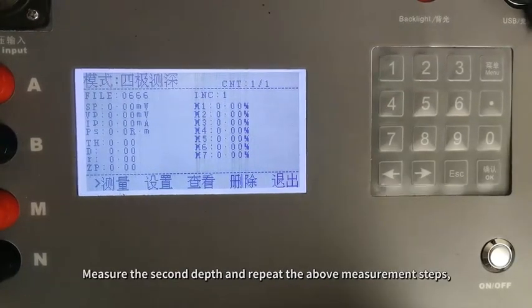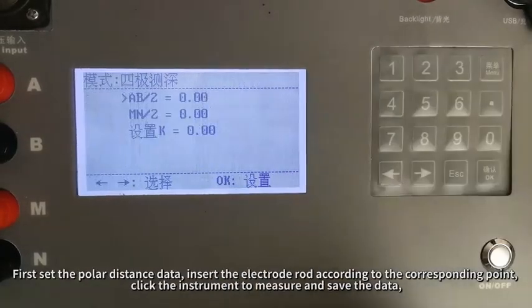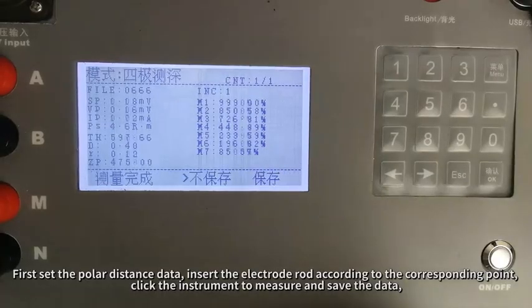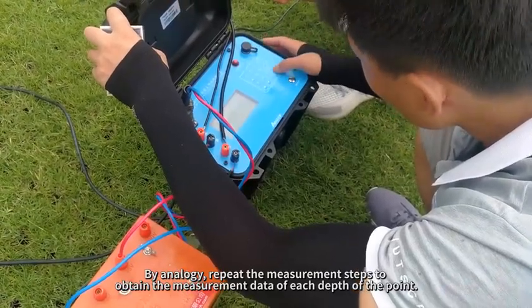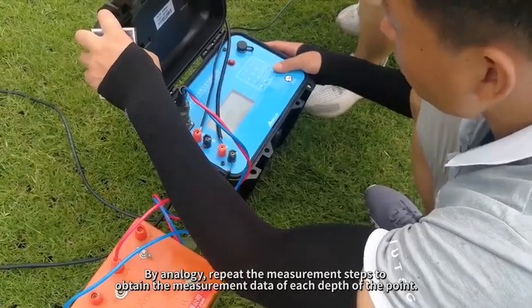Measure the second depth and repeat the above measurement steps. First, set the polar distance data. Insert the electrode rod according to the corresponding point. Click the instrument to measure and save the data. By analogy, repeat the measurement steps to obtain the measurement data of each depth of the point.